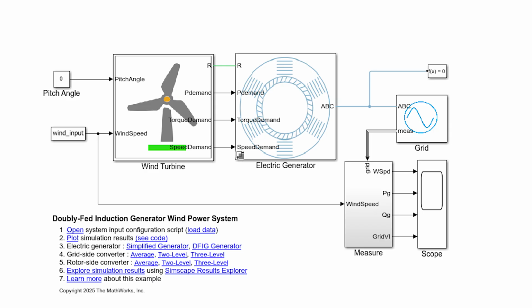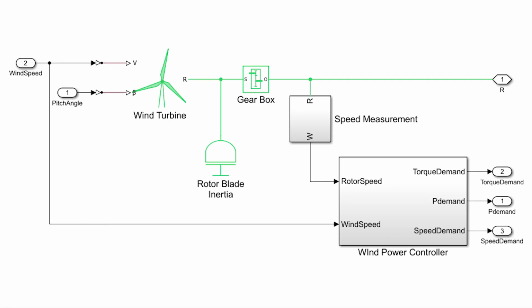These parameters can be entered into MATLAB using a doubly fed induction machine wind power system library in Simulink to simulate the expected behavior of the DFIG and its output. In this simulation, we have entered the 12 wind data points for our wind speed seen feeding the wind turbine, which will then calculate the expected mechanical power transmitted through the 1:72 gear ratio gearbox.